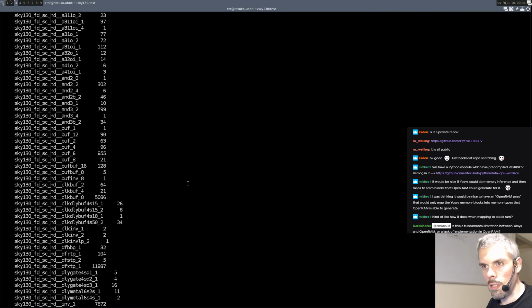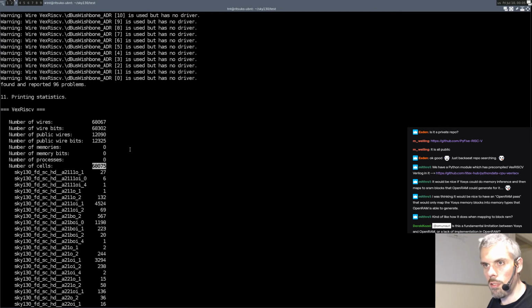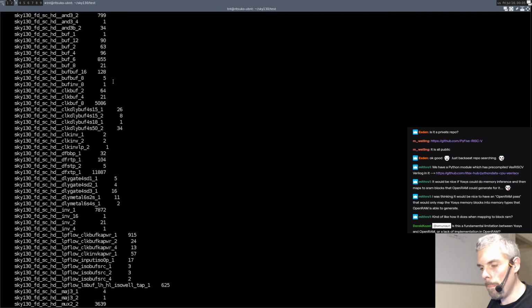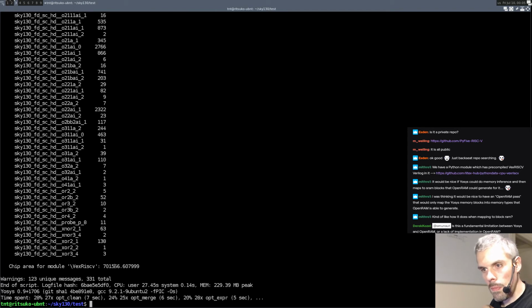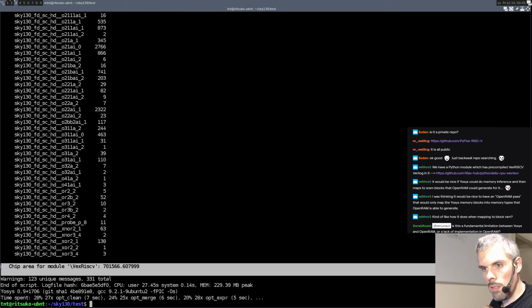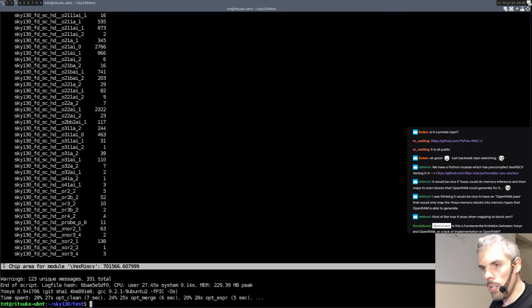And I know this processor has a bunch of memory, and you can clearly see that it has been implemented as flip-flops because you have literally 11,000 flip-flops in that design. 8,000 of them are going to be the 1 kilobyte instruction cache. And then the other 3,000 are the actual CPU, basically. And interestingly, I have no idea how accurate that is, but it does generate an area estimation.